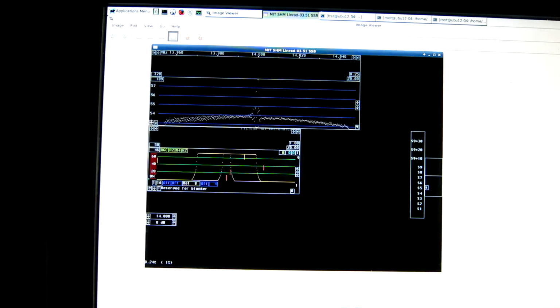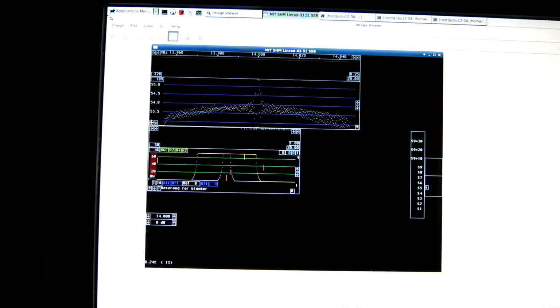And now you can see we have from here to here about half a decibel or maybe a little more. To see this better, I will increase the averaging, and to do that I have to increase the storage time for the transforms.